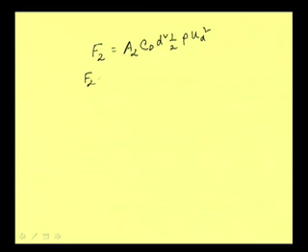Again, let me just keep this equation here, F2, for our convenience. We were writing that F2 = A2 C_D d² times half of rho u_d². Now let me replace this term. We can write this as A2, which will remain as it is, and then C_D we can write as a function, say f2, of u star d by nu, the kinematic viscosity. The diameter d square we will keep as it is.